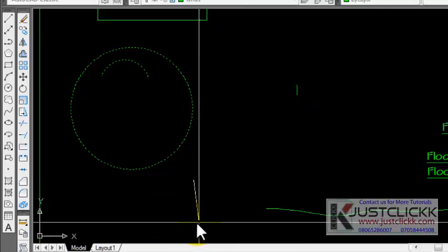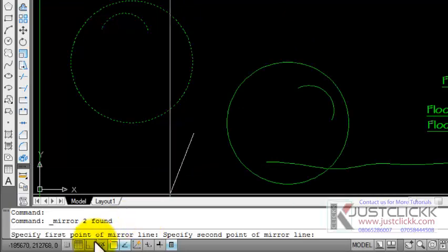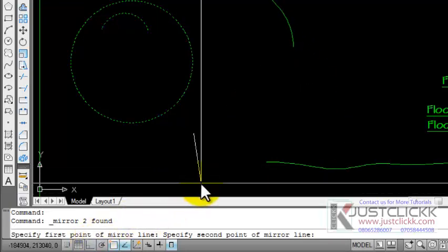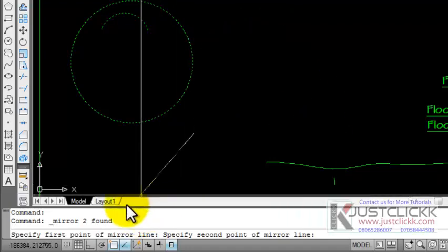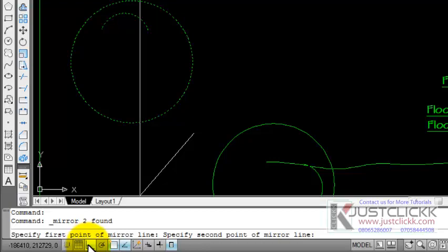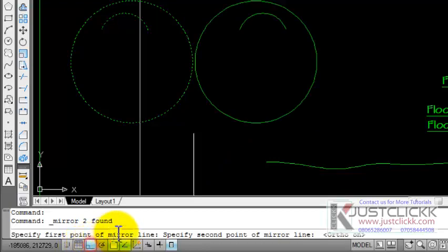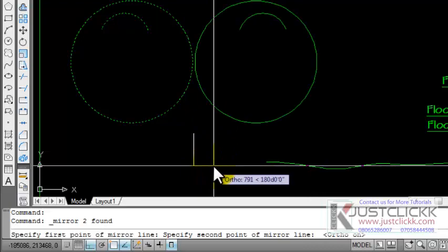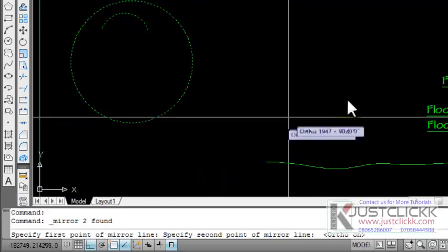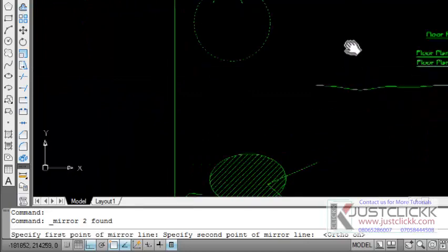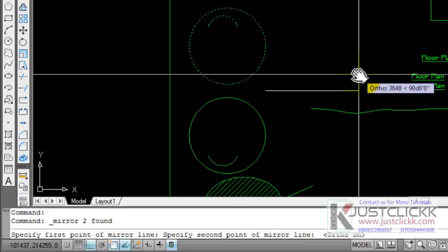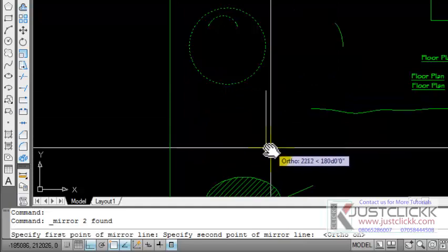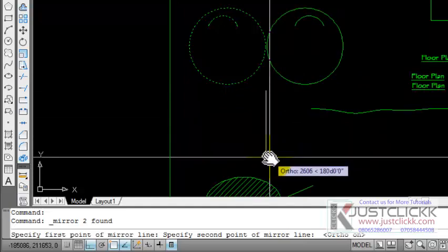You can achieve a better mirror object if auto is enabled. Auto is not enabled, so I'm not able to get a purely horizontal and vertical flip of the mirror. So let's click on auto here on the drawing aids. Click on auto and then you see that auto is enabling a better preview of your mirror. So if you mouse over, let's zoom down a little bit so that you'll see the preview. If you mouse over horizontally, you see the object will preview in the opposite corner below, and if you mouse vertically, you see it previewing the other side as well.